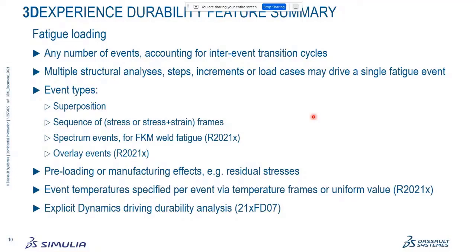You can include preloading effects or manufacturing through residual stresses. Temperatures, you can specify via the temperature frames that match the stress frames or provide a uniform value. And we support driving durability now from explicit dynamics.